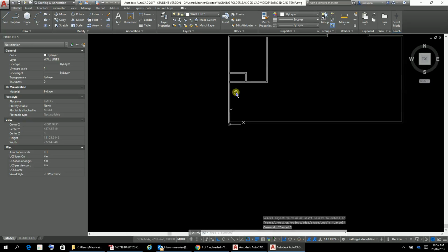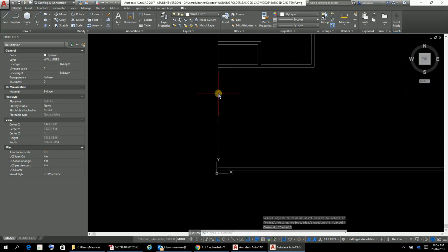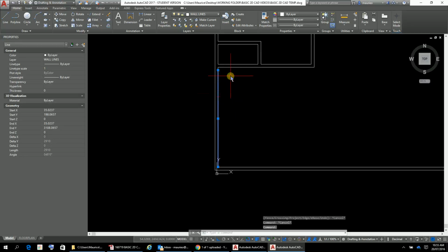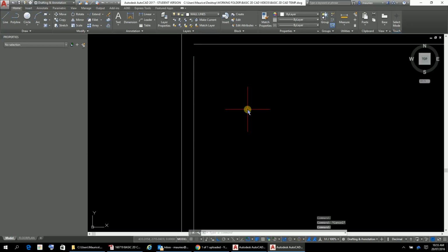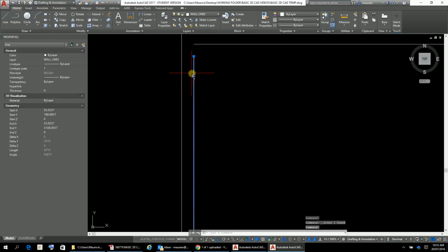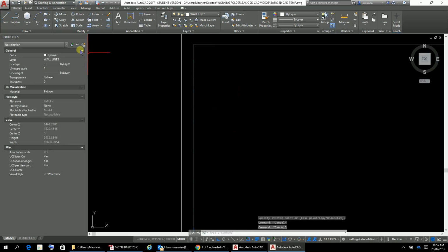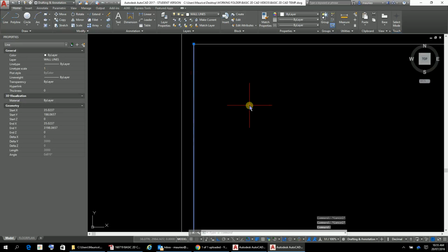I might have a little bit of a problem in here, in that we've got that line there, but it's not going all the way through. So what I'm going to do is delete that one there, bring this line here through to here, and now this should have an internal dimension correctly of 3, which it is.